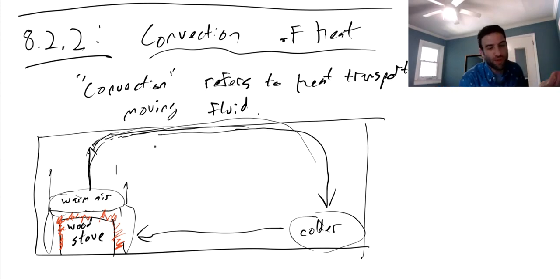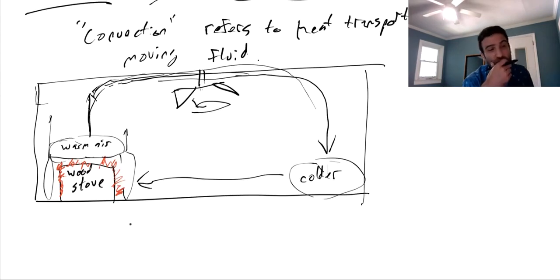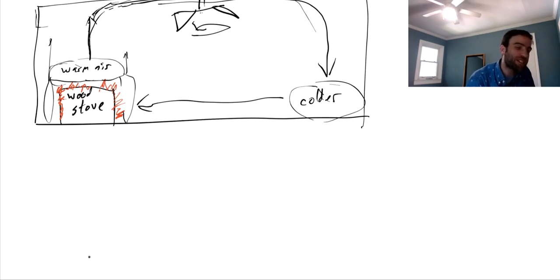Now, of course, if you're heating up a room and this is all you do, you just end up with hot air at the top of the room and cold air where you are trying to sit or enjoy your dinner. And so in actual room systems, you would install a big fan that would spin around, that would blow still-warm air down and create a better pattern of convective heating for at least the floor level part of the room. You might say this feels a little bit bland, but actually we've just explained why there's wind on Earth.